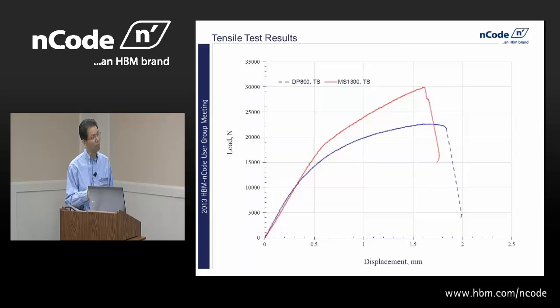But what happens at this load? The linear elastic response goes straight up here. We can consider it at this load level, but the displacement and load in the linear elastic case at this point are different from the actual ones, so we have to convert that. That is the main process we're doing.